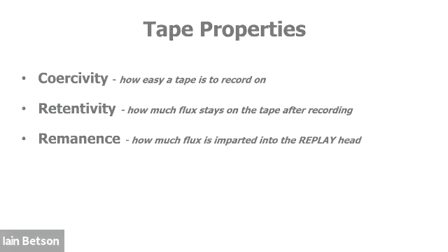However, tape, once recorded, will always hold its magnetic signal. It will hold it forever unless it is subject to another external field that will turn those magnets in another way and destroy the signal. It will always hold that signal. The only other way it can lose the signal is if literally the oxide drops off, with things such as sticky shed syndrome, and the oxide comes off the tape.